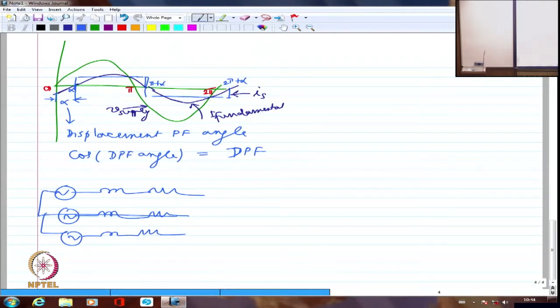And the solutions also lie in power electronics ultimately. So we create the problem, we also eliminate the problem ultimately with power electronics. I will not go into any more of that. Yes, sir. If I am talking about square wave, that is the current actually drawn by the converter, which I cannot eliminate. Because of that, I will have harmonic currents.